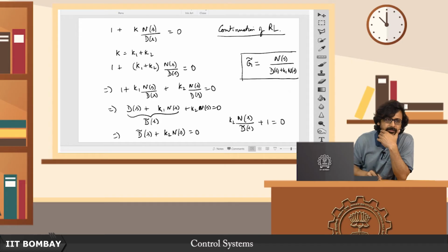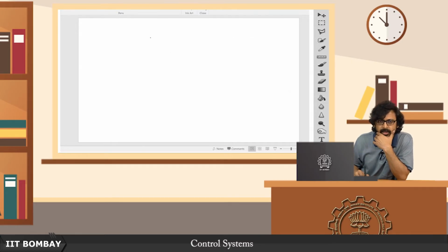So just as an illustrative case, suppose there was this point where there are 3 repeated poles, and we know that the root locus exists on either side of this on the real line because of the even-odd rule that we have already spoken about, one of the early rudimentary rules.